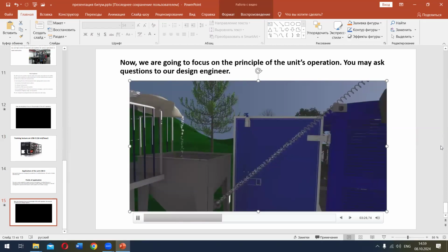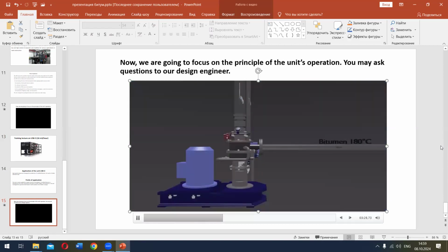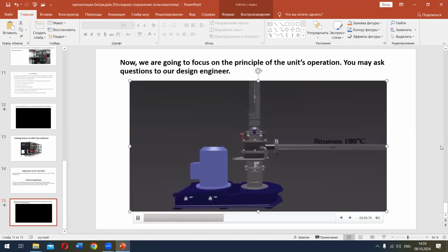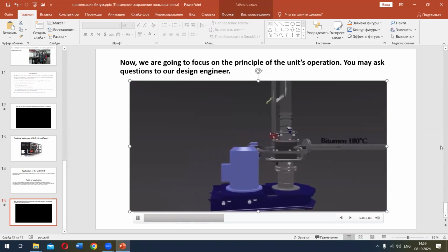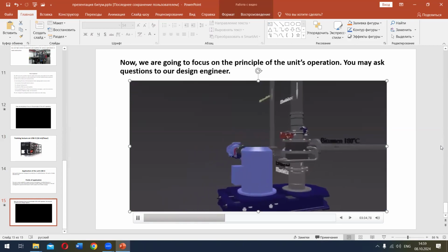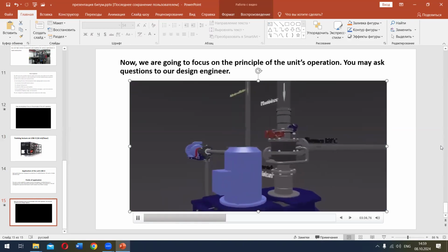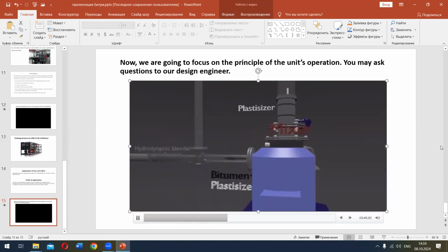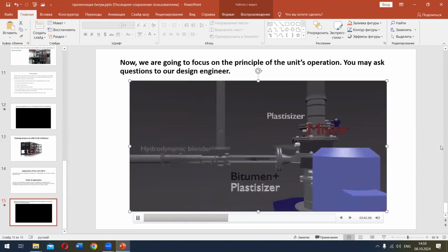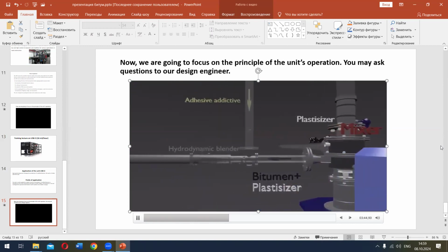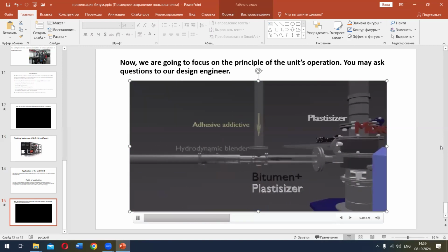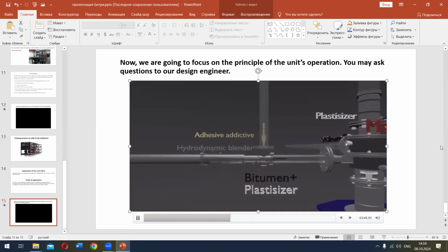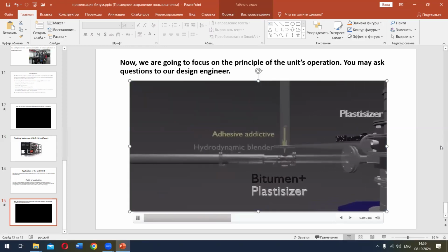The polymer preliminarily filled into the hopper is fed by means of a spiral transfer with a drive and a screw feeder. Depending on the required polymer concentration in bitumen, the operator has the ability to control the drive rotation speed of spiral transfer and thus adjust the polymer feed. Entering the mixing chamber of screw mixer, the polymer is wetted with bitumen.